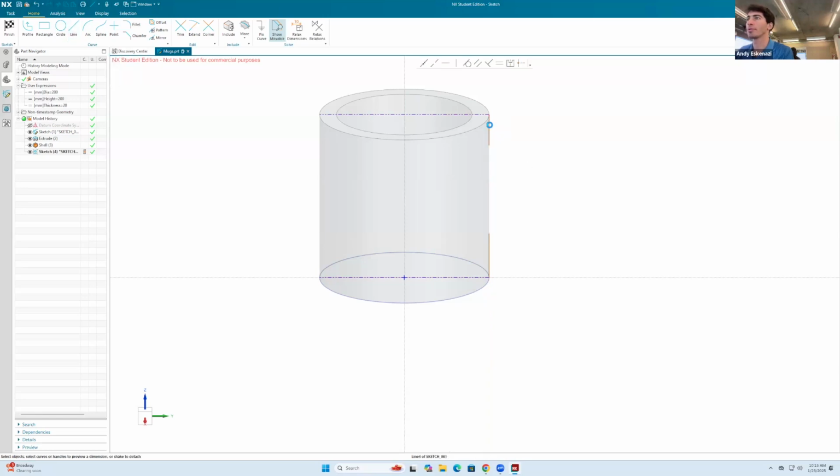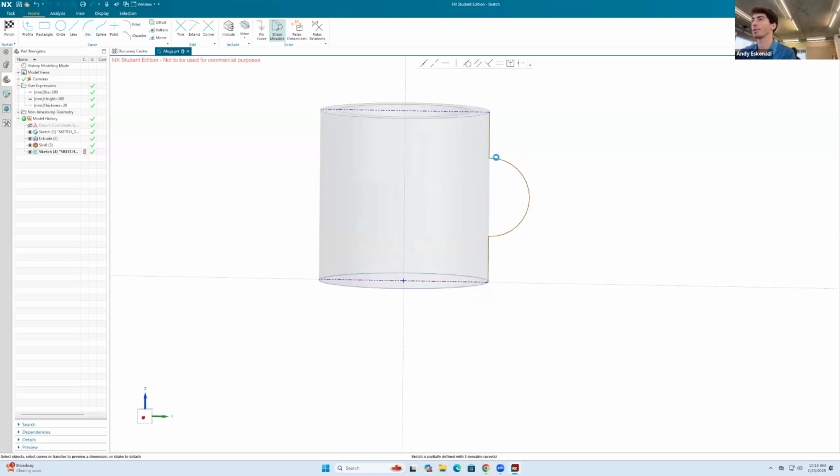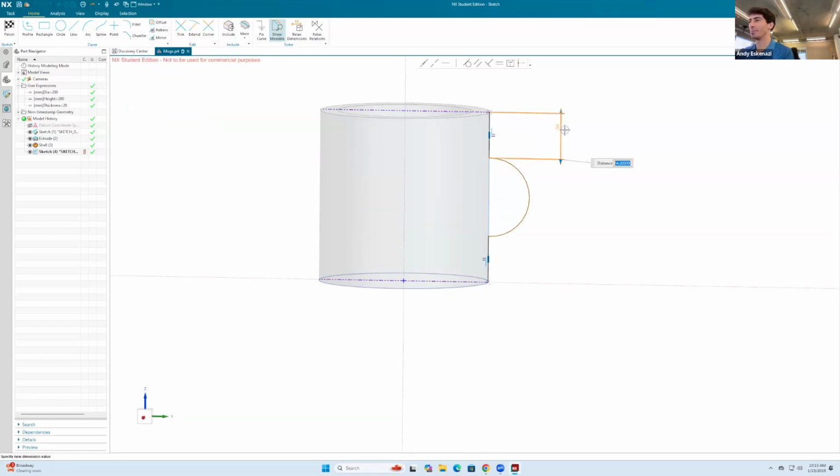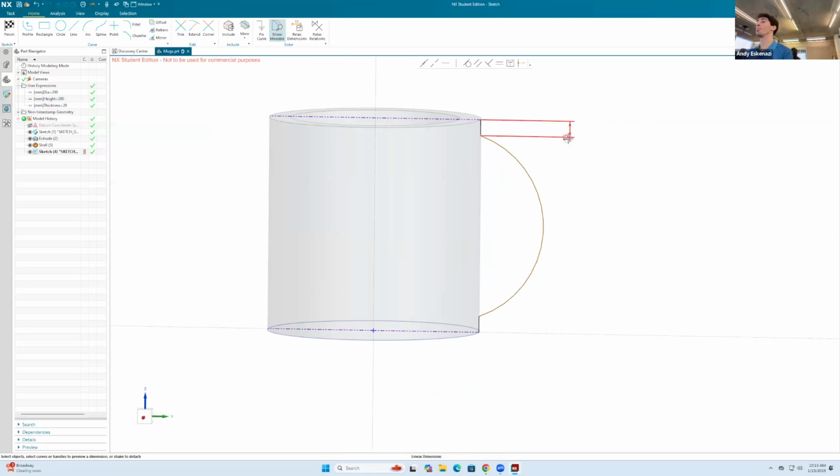I'm just drawing two lines. I'm gonna click on the equal command, and I'll make these two lines equal length. You'll see why I'm doing that in a second. And then I'll make an arch right there. That's a sad arch, as you can say. But I'll make this line in here be, let's say 10, actually 15.